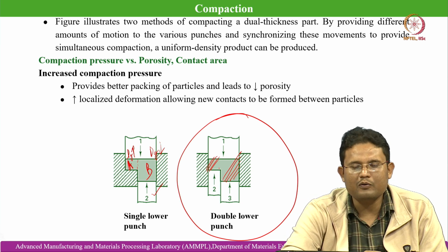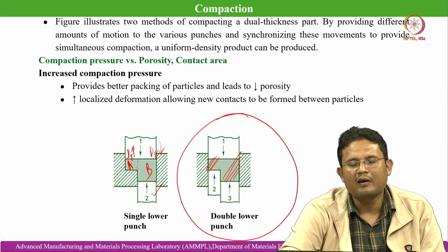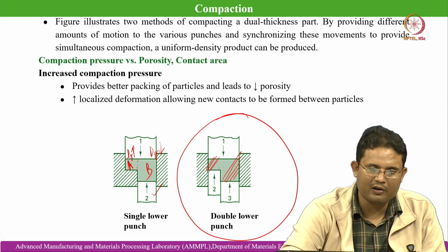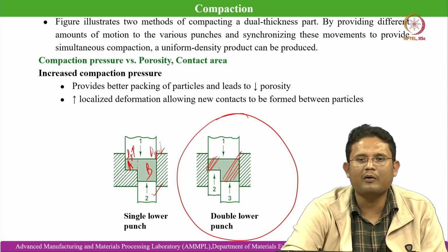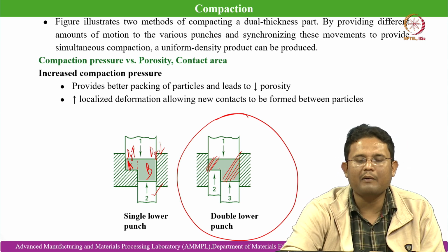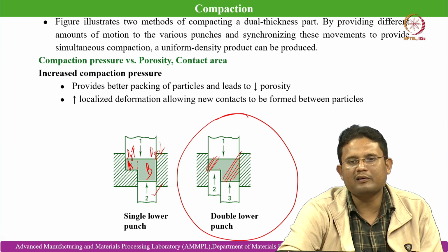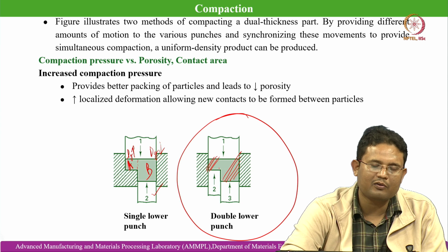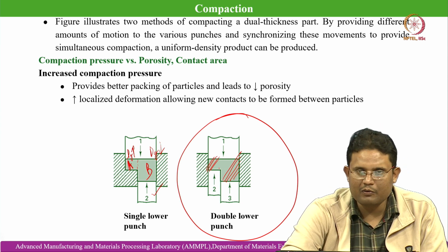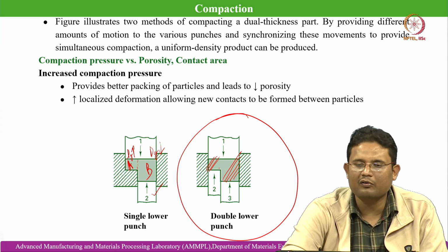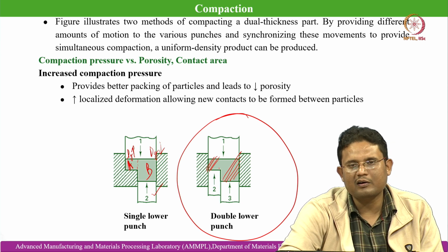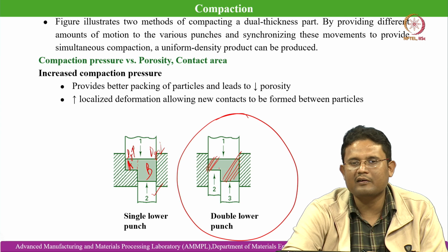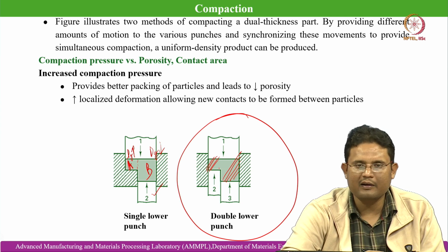The diffusional mass transfer starts during the thermally activated sintering process, and also these are the locations from where the neck formation starts between the neighboring powder particles. Thereby we achieve uniform densification throughout the part, and we achieve uniform density in the sintered part, which is also a primary requirement for utilizing the parts for desired functional or mechanical applications.